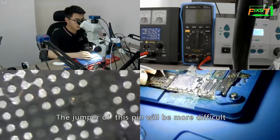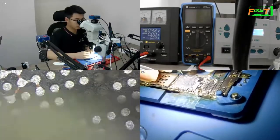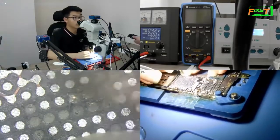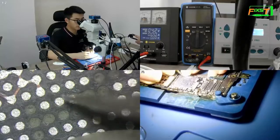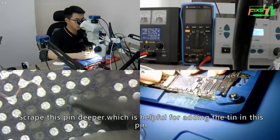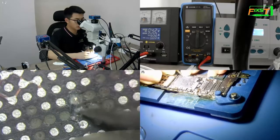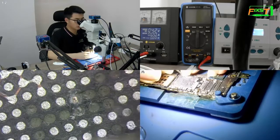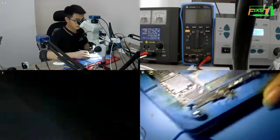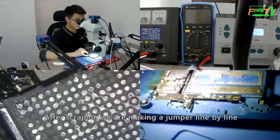The jumper of this pin will be more difficult. Scrape this pin deeper, which is helpful for adding the tin to this pad. After scraping, we make the jumpers line by line.